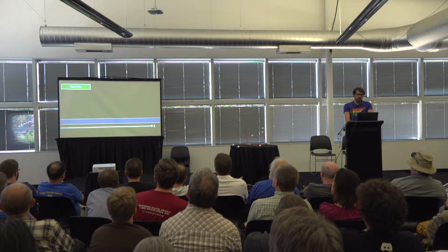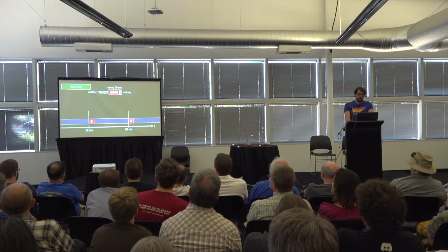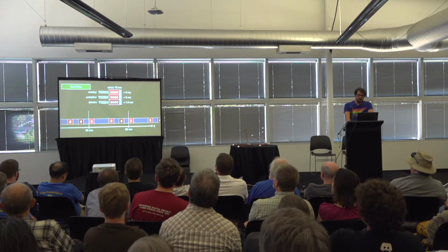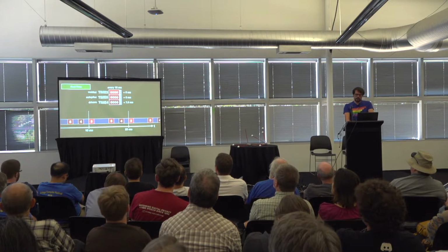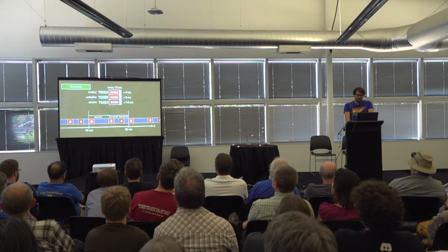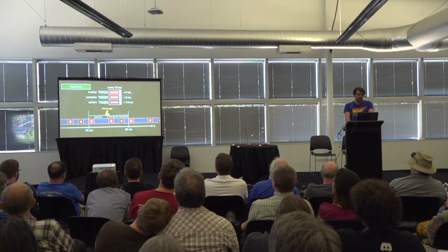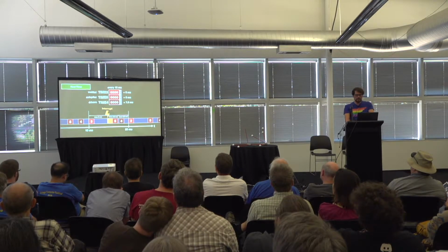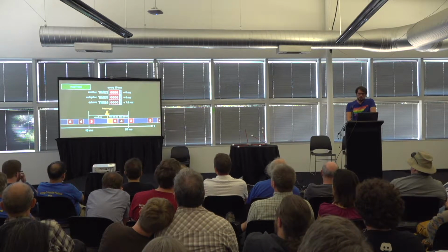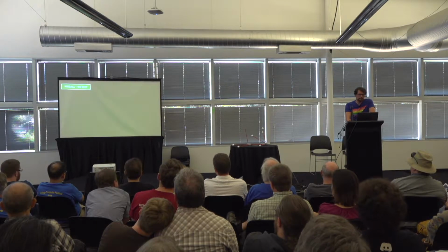The timer that controls the waitlist has a granularity of 10 milliseconds. Other timers can fire at the same rate, but are offset. And the work triggered by them is designed to be short enough to never overlap with the next potential timer-triggered work. This is complicated by device interrupts, which can come in at any time. The duration of an interrupt handler causes latency, and the maximum duration will reduce the allowed time for the timer handlers. The core system software makes no guarantees about the timing. It's up to all the components to cooperate so that the real-time goal can be met.